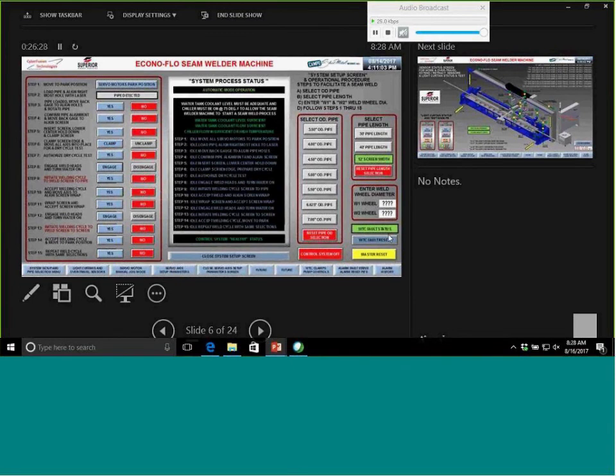And the cool thing here, with what we created, we have a weld diameter, and you'll see the weld wheels, that there is wear and tear that occurs. And so they'll put a mic on it, and then once they mic it, they know what the OD size is, and then based on usage, obviously they're copper heads, so those will diminish a little, and so they simply remic it. They put in the new weld head diameters, and then the machine will automatically adjust on the fly to the correct angle, so therefore we always get a good contact for the weld.